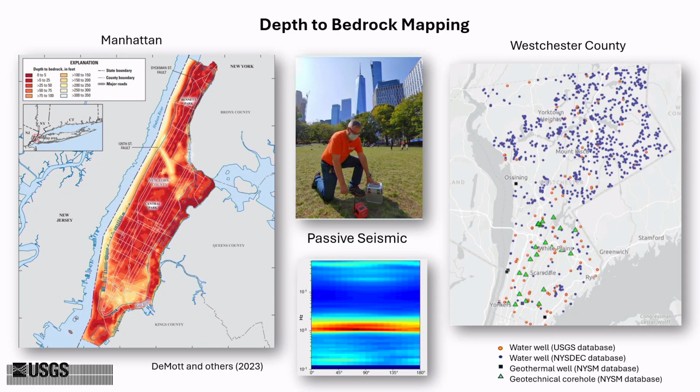Of course, depth to bedrock mapping is an important component of the investigation, and we have a leg up in the southeast New York study area in that we've published digital depth to bedrock and overburden maps for the 5 boroughs, which include Manhattan and the Bronx, which are our focus county areas in that area. These maps were developed from thousands of logs from borings. As you can imagine, in New York City, there's a lot of construction. So we've taken that information.